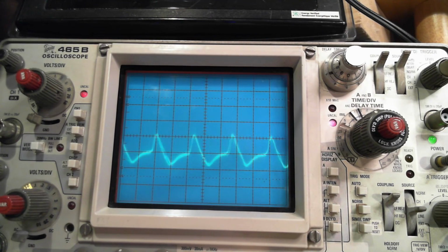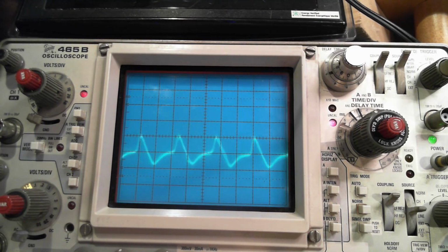I cannot make my scope trigger, so it's going to march across the screen like that. So I'm going to try a few things. First of all, I'm going to reduce the modulation level, see if that is somehow part of the picture. The answer is no. So that's not my signal generator. I know my signal generator produces a beautiful sine wave. That's what's going into this radio receiver. Now I'm going to tune the radio back and forth.